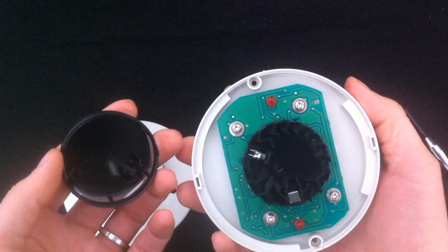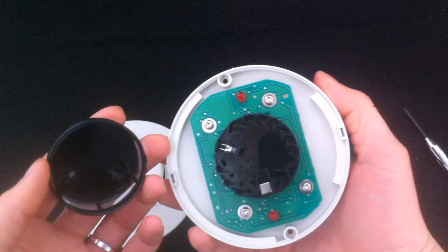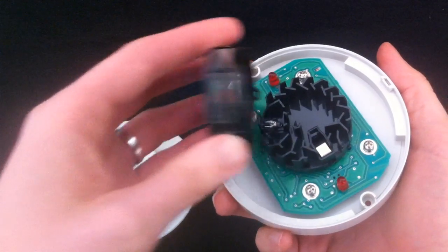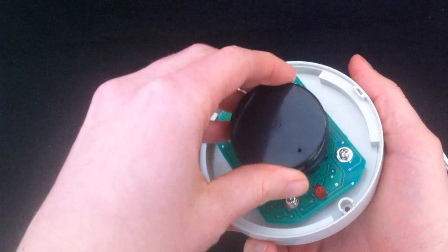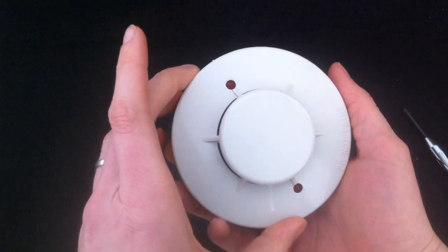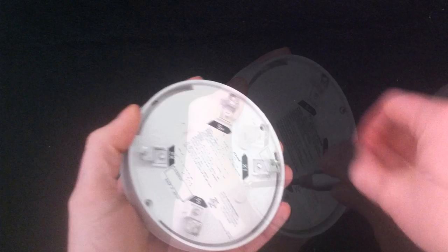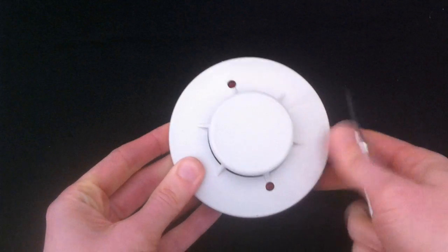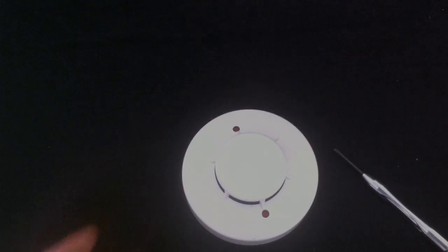With compressed air or a small vacuum, you can clean out the chamber. You may also need to clean the bug screen itself. Once the device is clean, replace the bug screen, making sure that it is clipped, and then replace the cover of the detector, replacing both screws that you removed in the beginning. You can now return the detector to the base and rerun the sensitivity report. The detector will now show a clean sensitivity.